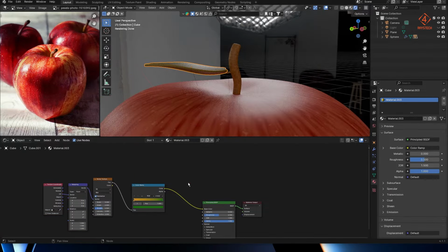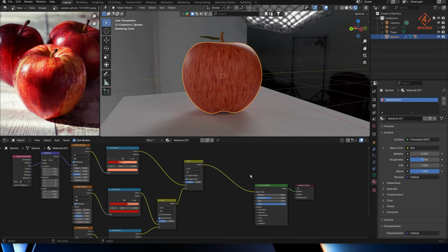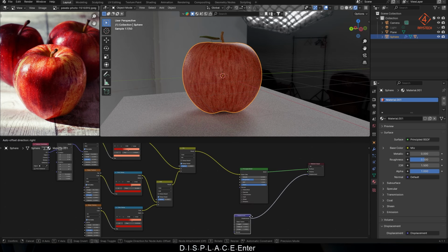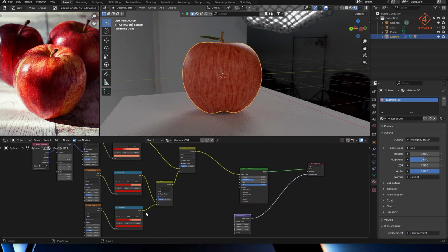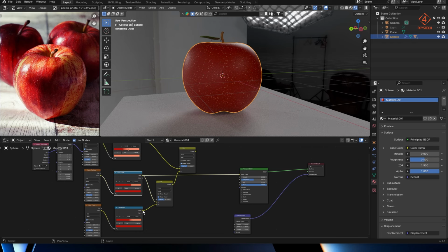Keeping the approach the same, so you can practice the same thing again and again and get a bit more hang of it. Okay, let's pick up a displacement node from this material of apple that we've created. This time we're working on aging, so we'll create those aging dents. I've connected the output of the bigger noise that we created first and now the smaller noise, so you can compare the two side by side.